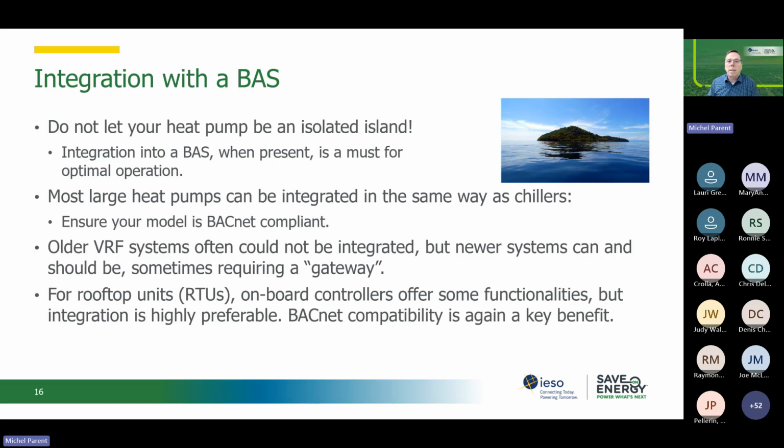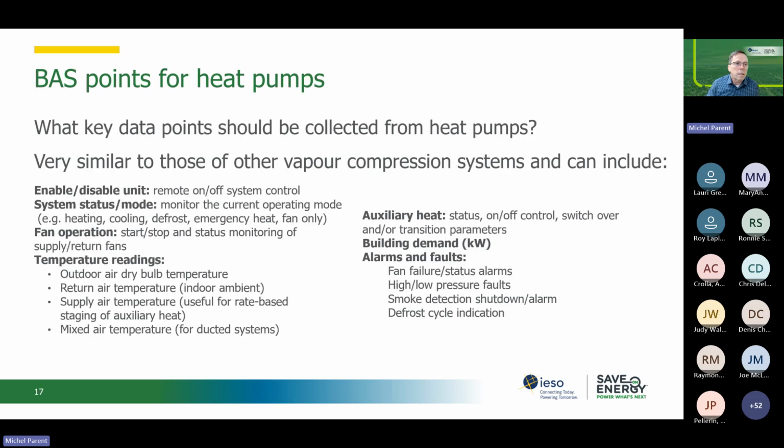Obviously, if your BAS is not BACnet compliant, you can always get something called a gateway, which is kind of a translator between the OEM controller, the original controller from the manufacturer, and your BAS. But you really want to stay away as much as possible from those gateways, which are really translators between the machine that you bought and your BAS.